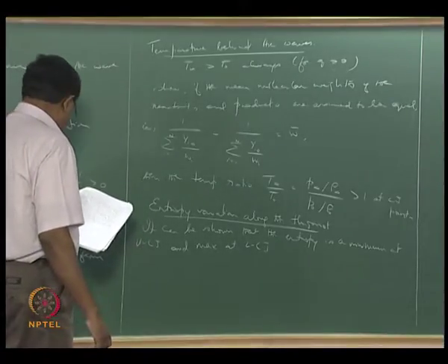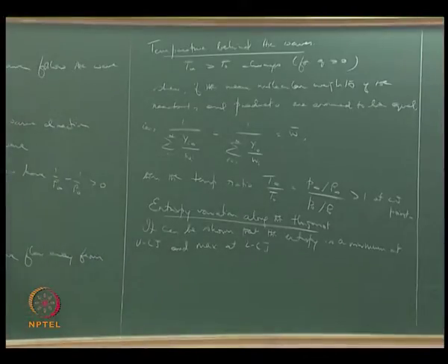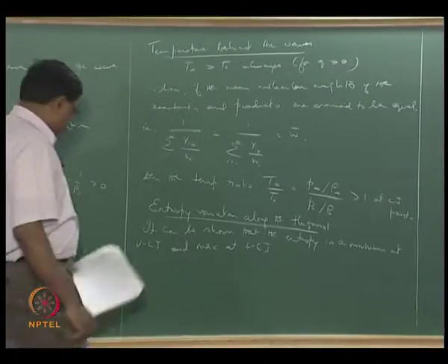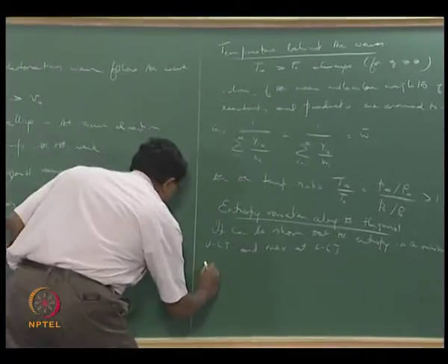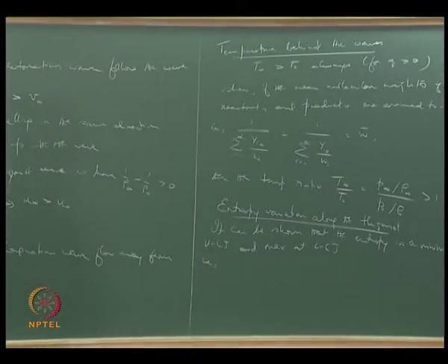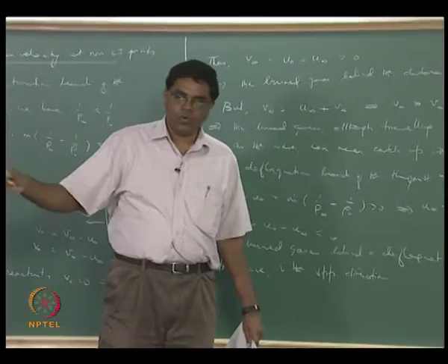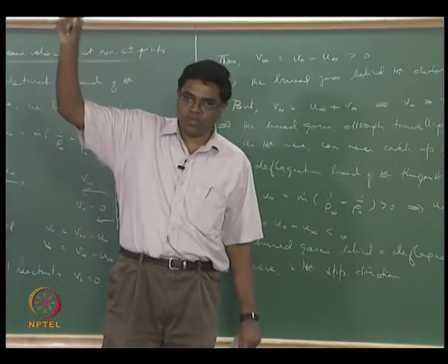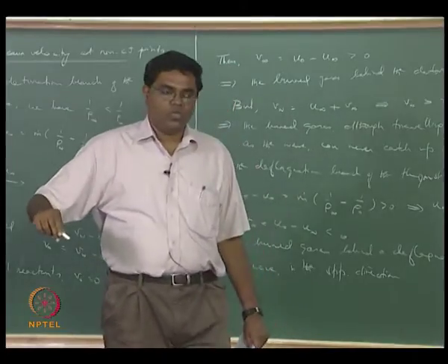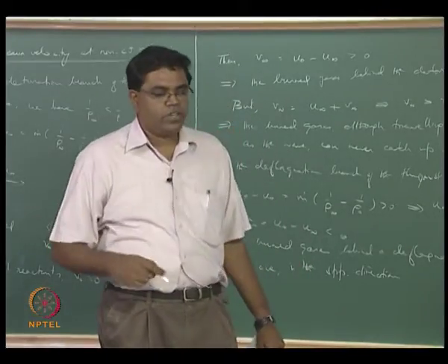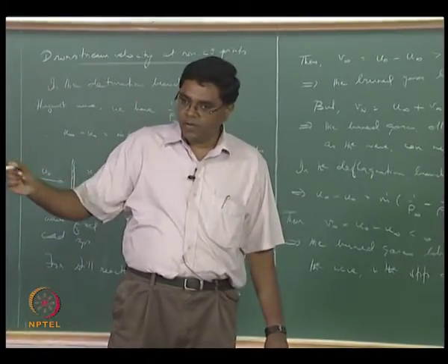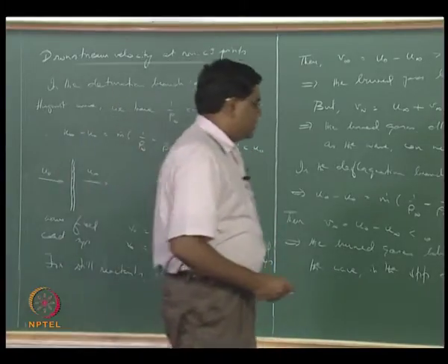And then how do you show this? Okay, so I'm not going to show this, but you can show. Question is, how do you show this? Well, it's rather straightforward. What you have to do is you see that the Hugoniot curve has P infinity on the vertical axis and 1 over rho infinity on the horizontal axis. So it's as if 1 over rho infinity is your independent variable and P infinity is your dependent variable, right? So what is suggested is you now try to express your entropy as a function of 1 over rho infinity as an independent variable still.